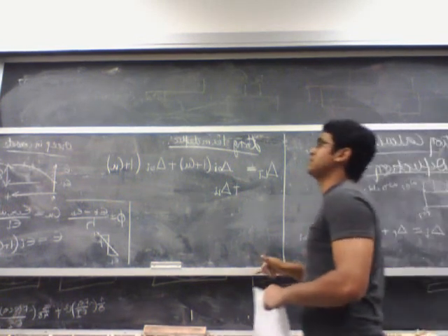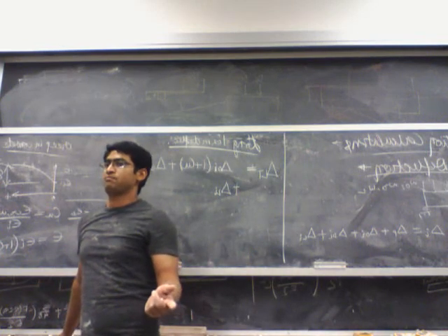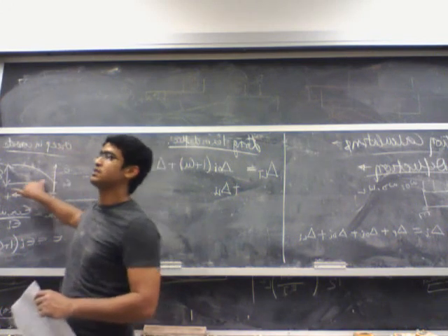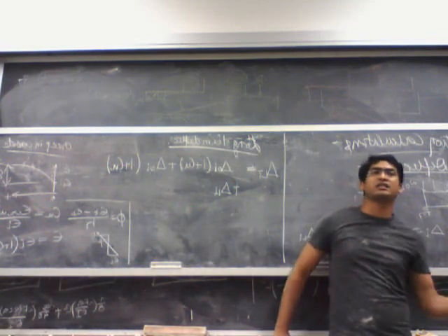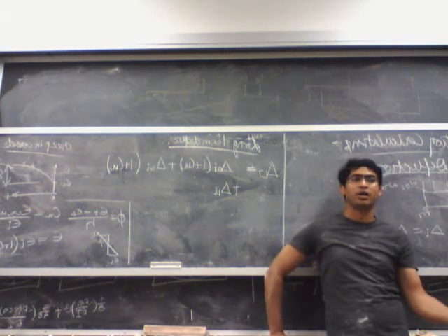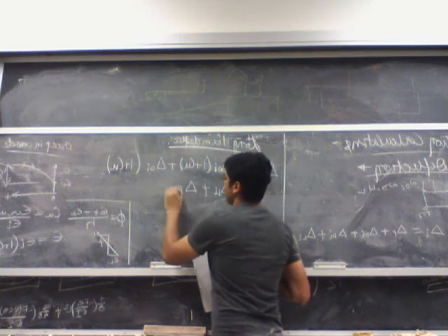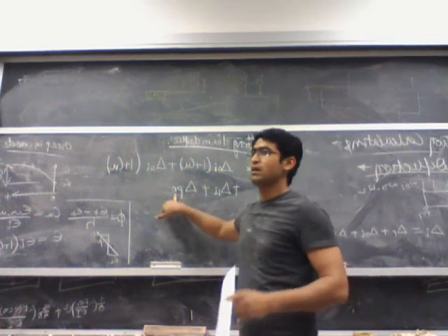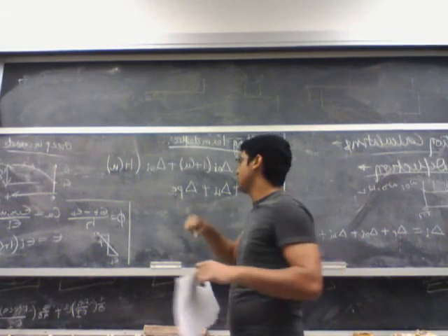The one problem with pre-stressing strand is the force in the pre-stressing strand itself changes over time. So instead of just the force being constant and the strain changing over time, for a pre-stressing strand, both the force and the strain are changing over time due to stress loss in the strand and creep in the concrete. So the way to account for that is, you say my initial deflection is due to the effective pre-stressing force, which is F. I think during the lecture he said this as delta Pi.